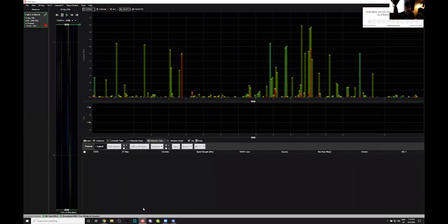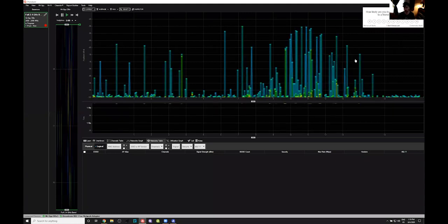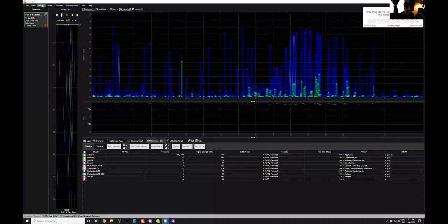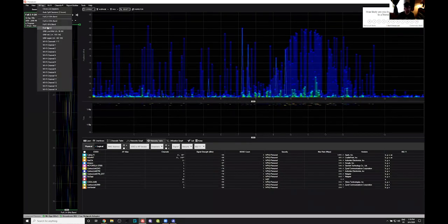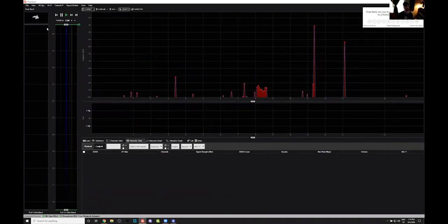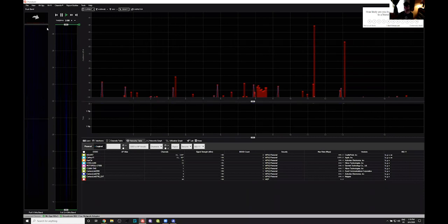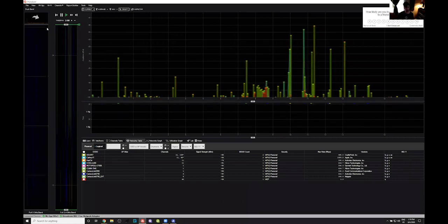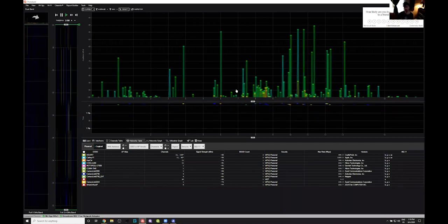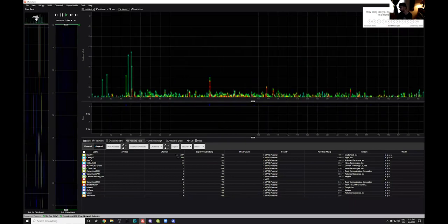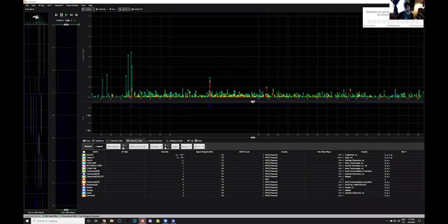So when you first open up Chanalyzer, it actually starts sweeping the 2.4 gigahertz band only. To remedy that, you go to Wi-Spy here at the top left and just select dual band if you want to see both the 2.4 and the 5 gigahertz band. So this will dedicate the resources of the Wi-Spy DBx to sweep both bands simultaneously. And so here we see the 2.4 gigahertz band. To toggle between the two, you just click the arrow in the top left corner over here. And so now we're looking at the 5 gigahertz band.